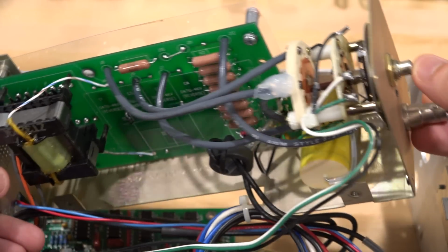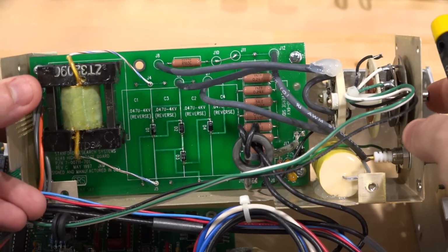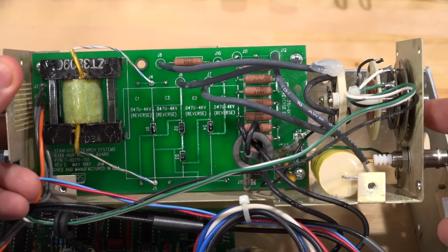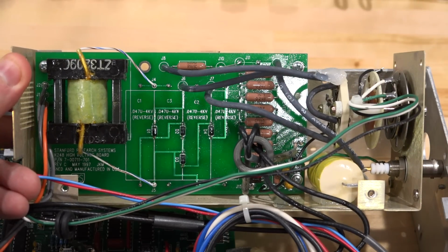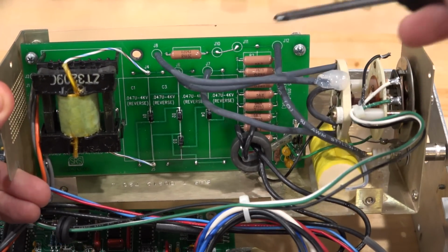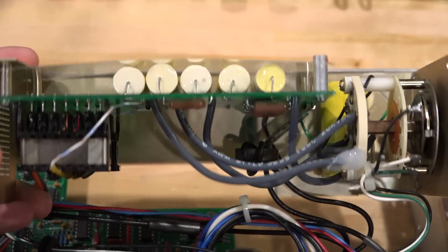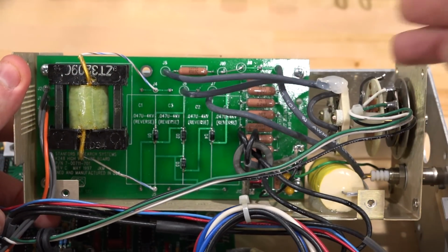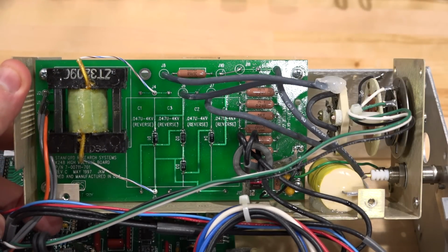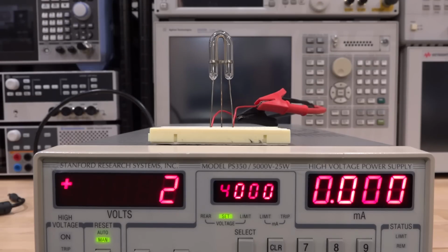And here's the switch over here that flips the polarity and gives you negative voltage below the case ground of this instrument. So everything matches perfectly to what we saw in the schematic. And all these resistors will make up the voltage divider as well as the current monitor. Yeah, looks nice. We just have to make sure we put it back carefully because obviously this needs to be very well protected. So let's do a quick experiment taking advantage of the trip and current monitoring capability of the power supply, which can be quite helpful in overloading conditions.